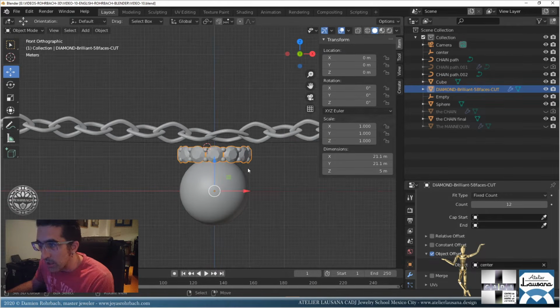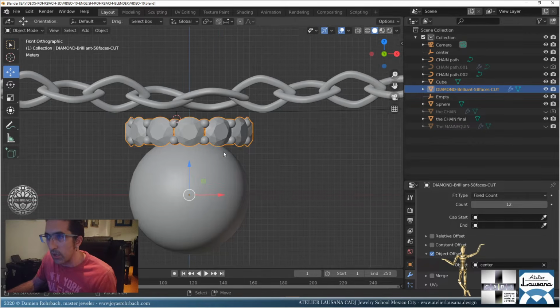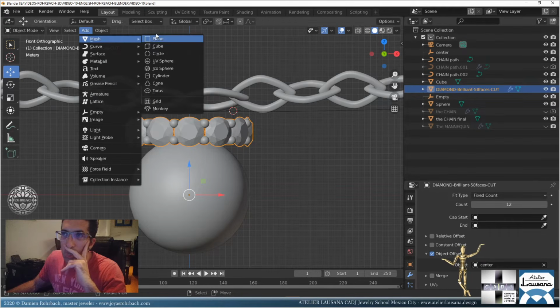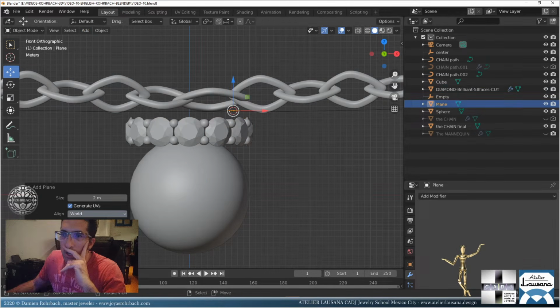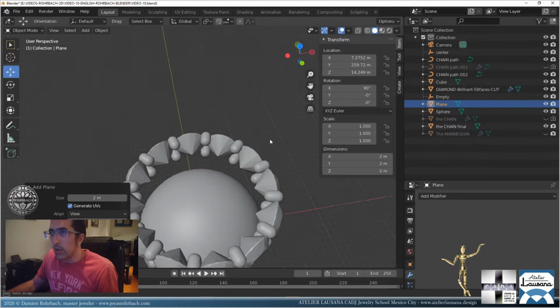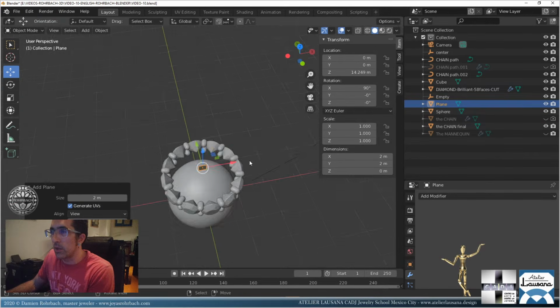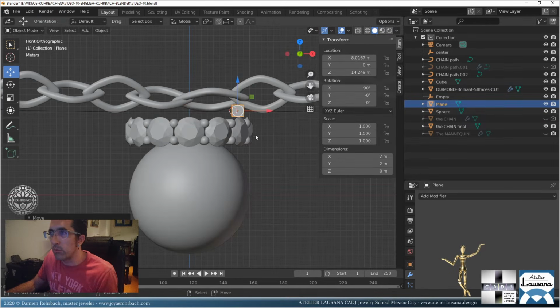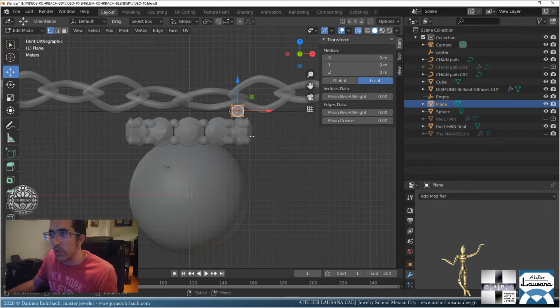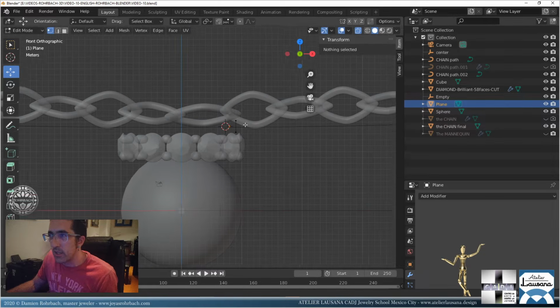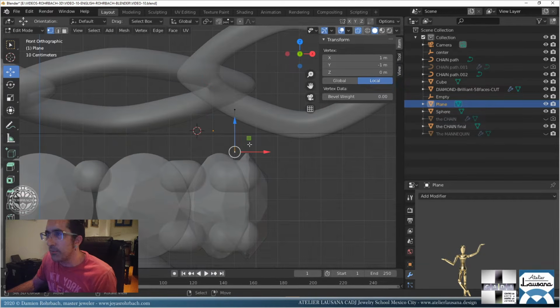But we need something to put that over the place. All right, let's go here. Let's create a mesh plane. Align to a view. There you go. Let's check that we are center on X, Y. All right, so let's go about here maybe. Edit mode, Alt Z. Okay, let's remove this and that. Suppress vertices. Now we basically need a ridge.